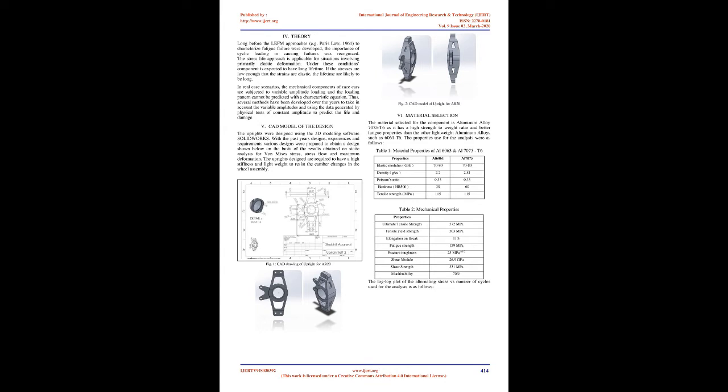simulated for the application could predict how long the component will function with the forces acting on it, and helps the designer to replace the component before catastrophic failures occur. Any optimization to the design based on the results of fatigue analysis could lead to an improvement in the life of the component, which adds to the quality of the design. The parameters used to obtain the results of the analysis are obtained by the respective calculations and analysis conducted by the team members of Automantra Racing, the official Formula student team of Galgotias University.